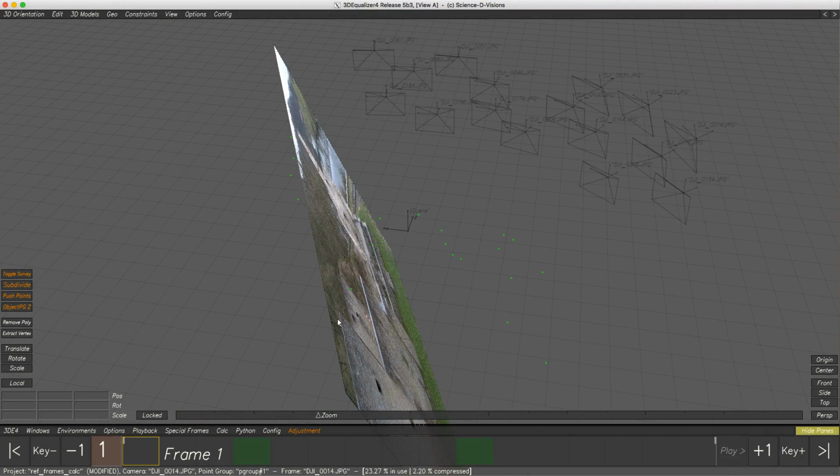Beside the reconstructed 3D points, we clearly see all reconstructed cameras in their positions in 3D space. As seen in footage, we have 3 rows. Okay, the reconstruction seems great. Just 3 quick modifications are needed to perfect it: distance constraints, scene alignment, and baking.